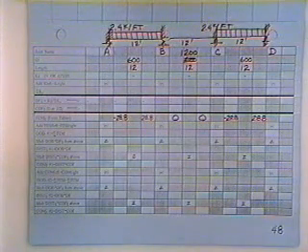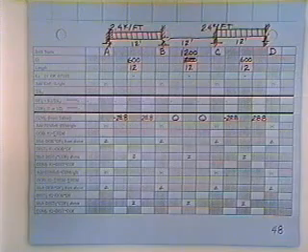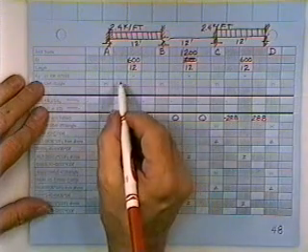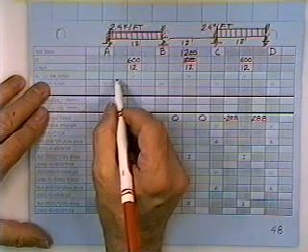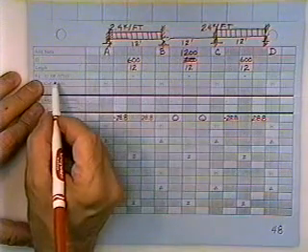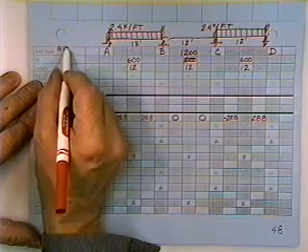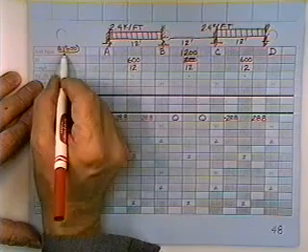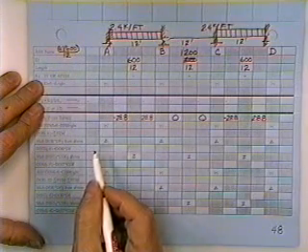Write that down right quick: nothing else there. All right, so we have to compute 4EI over L. 4 times 600 divided by 12, that's a third of 600, that's 200.